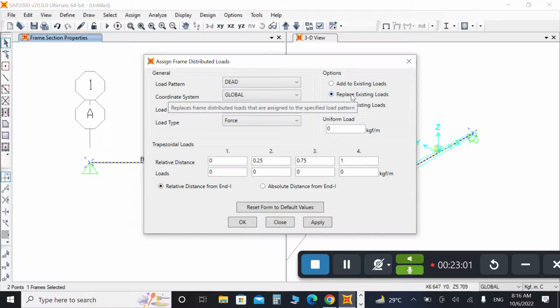So now we have to add new loads. Here we have 2 things, relative distance. For example, at 2 meter you have 3 kilonewton force, at 5 meter we have 4 kilonewton force. So you use this. In these next examples we will work in relative distance.